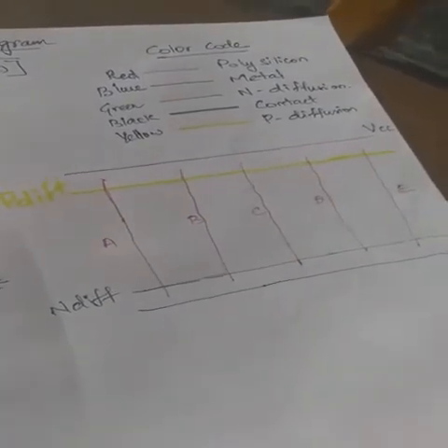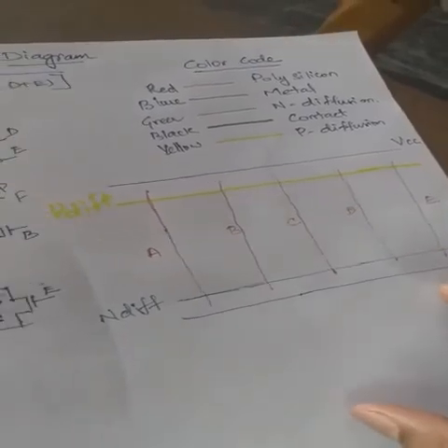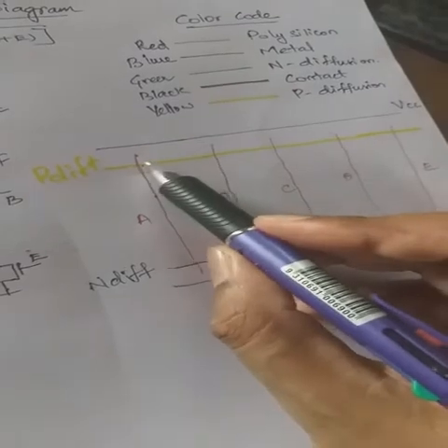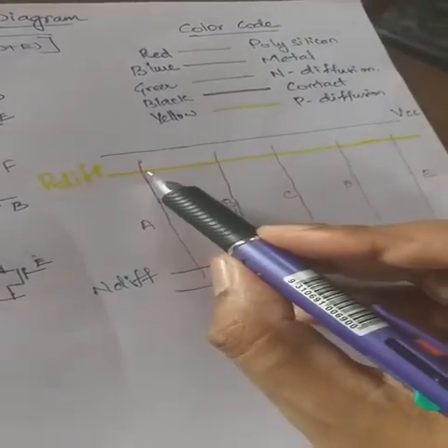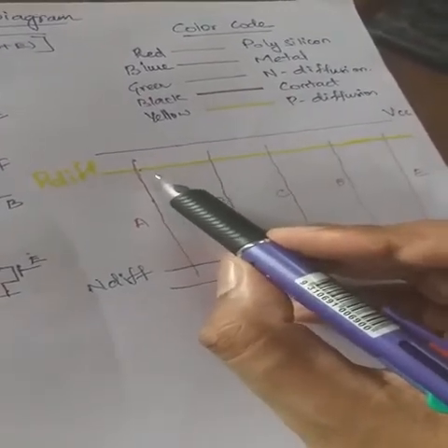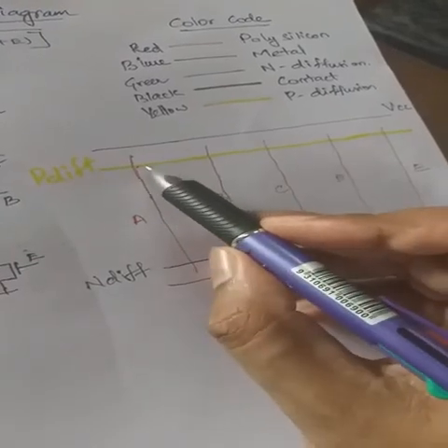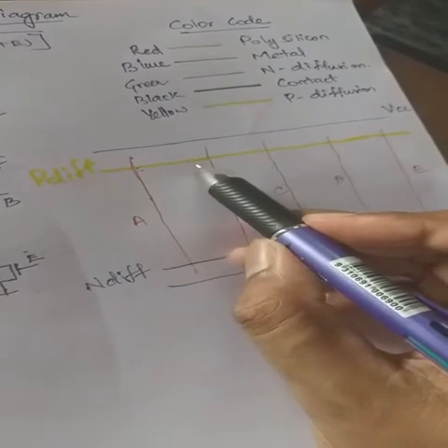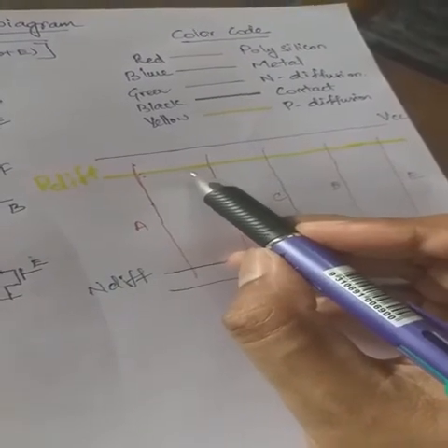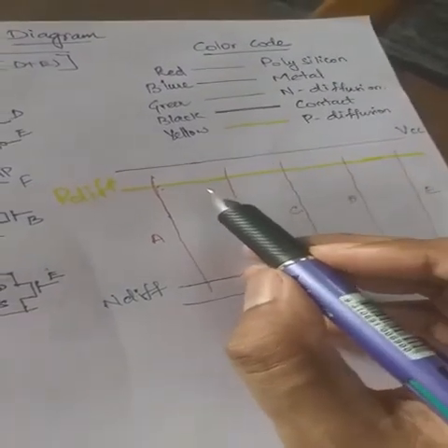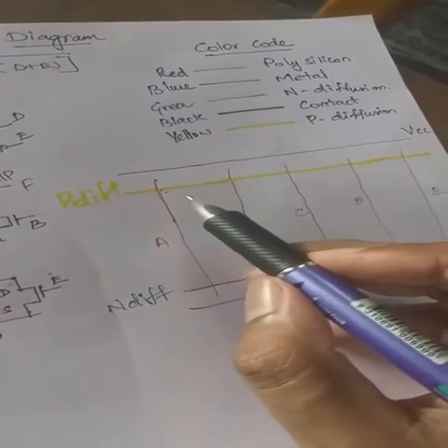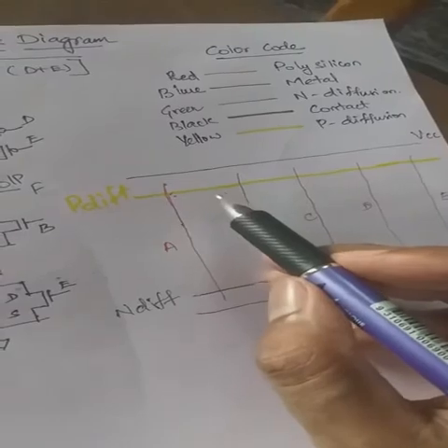The next step will be to mark up your source and drain terminals, right? This particular part is called a fused part. It means a terminal of A and B is connected. So from the static CMOS diagram, we have to look at which two terminals of A and B transistors are connected.